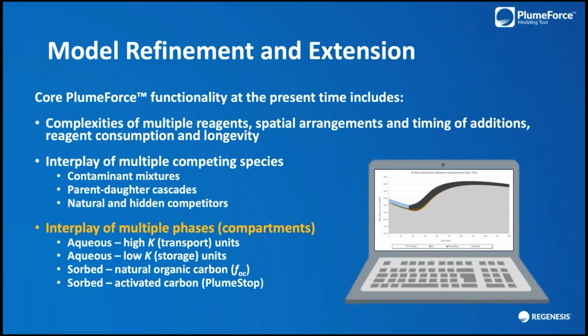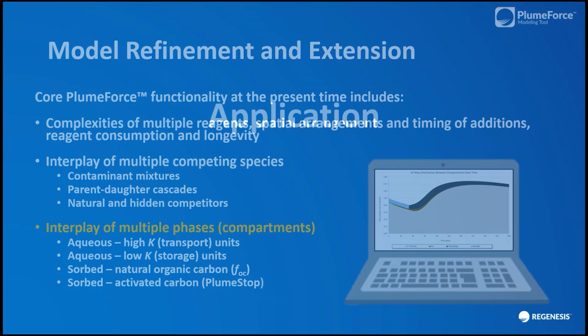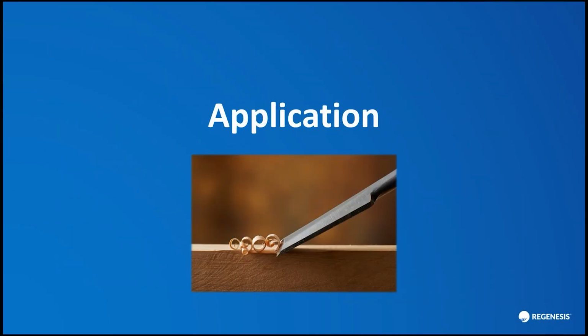And of course, it considers the mass that is sorbed onto the activated carbon of PlumeForce. Such multiple phase consideration is important because in many cases, relatively little contaminant mass is present in the groundwater, yet this is all we can generally measure. Like an iceberg, most of the mass is hidden, and we looked at the significance of this in the previous webinar.